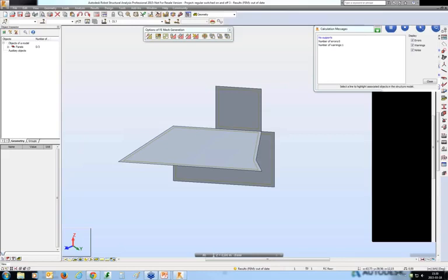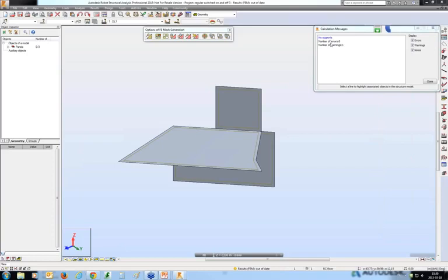So first I would correct this analytical model using the detailed correction option to structural axis. Otherwise, I would define the structural axis at the characteristic points of the model, like along the walls, at the level of the slabs, and then I would correct that. That's the first model that we covered during the presentation. Then if you update the Revit model, you will update the analytical model, corrected in Robot. So there should be no further issues with that.